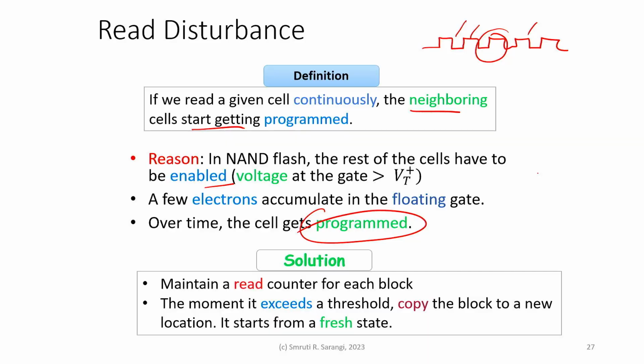Again, this can be fixed with a little bit of computer architecture, not software involvement but logic involvement. You maintain a read counter for each block, and the moment it exceeds a certain threshold, you copy the block to a new location.